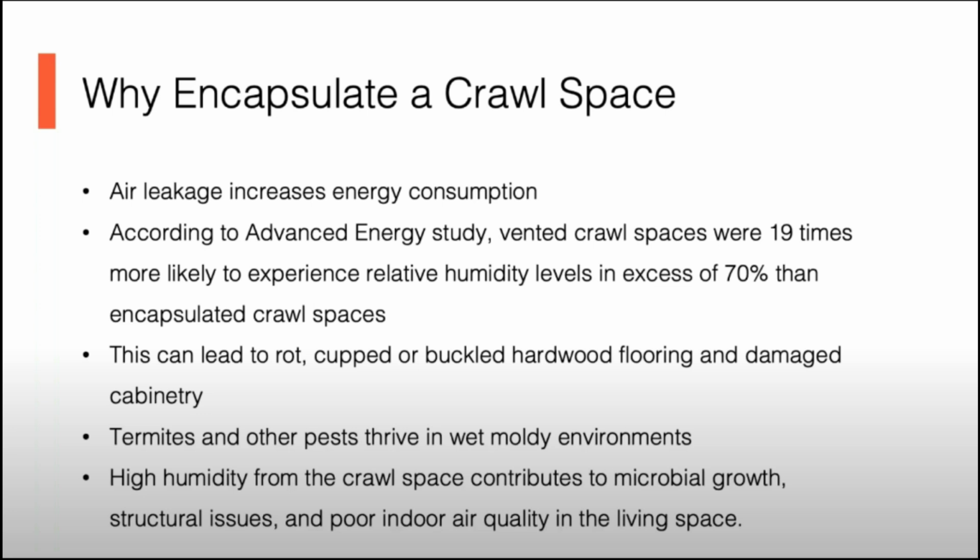One big reason is energy consumption. When it's hot outside and that air is coming in below the home, you're going to be heating up that space. In the colder times of the year, when you have a crawlspace that's ventilated to the outside, the insulation underneath the subfloor area isn't enough. The reality is, we're still bringing a lot of cold air into the house. This is another reason why energy consumption is a big reason why people encapsulate crawlspaces.